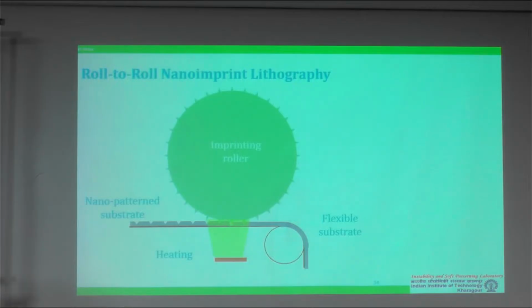It sort of exceeds the glass transition temperature. What is glass transition temperature to an engineer or thermal science engineer? Glass transition temperature is a temperature above which the viscosity drops significantly, right? So that it exhibits more like a liquid behavior. And then you do the patterning, fair enough, no problem.